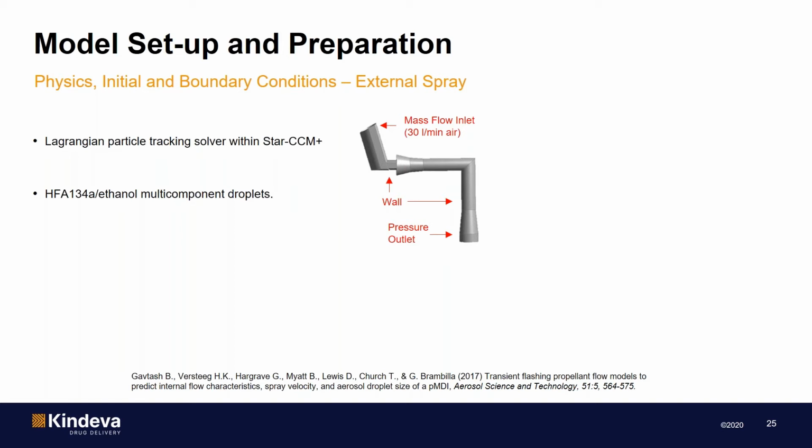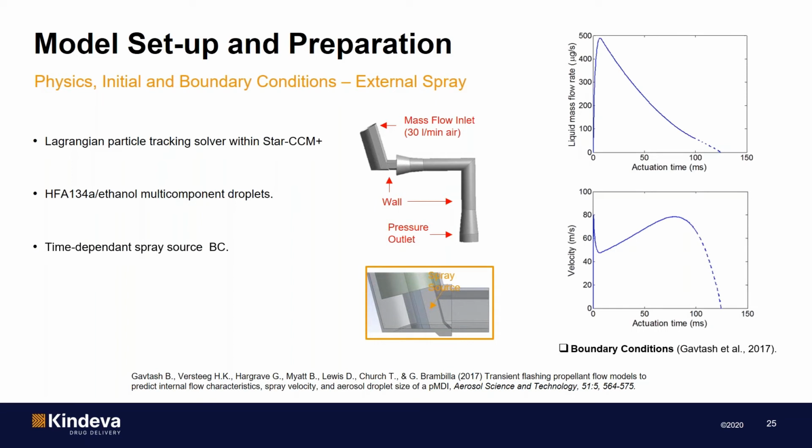For this type of modeling, we use Lagrangian particle tracking to simulate the spray dynamics. The droplets are defined as a multi-component HFA-ethanol mixture, and the spray source is constructed with time-dependent velocity and mass flow rate boundary conditions, which again are calculated by a separate model.